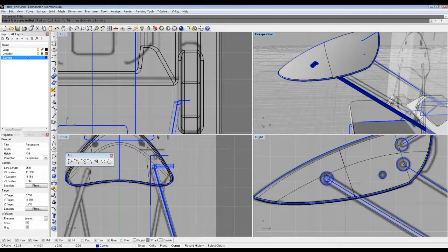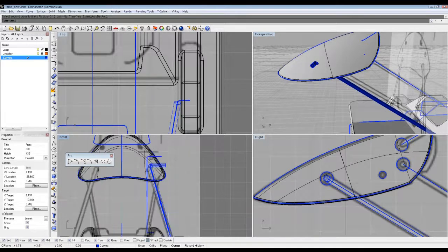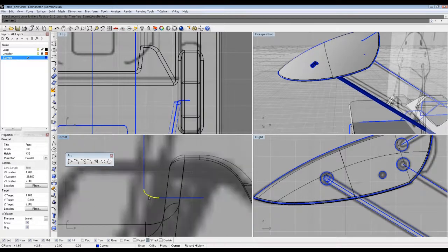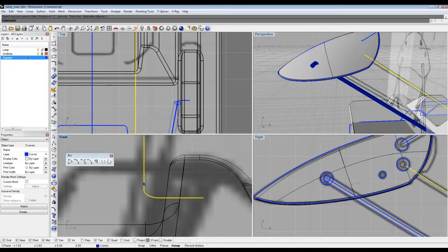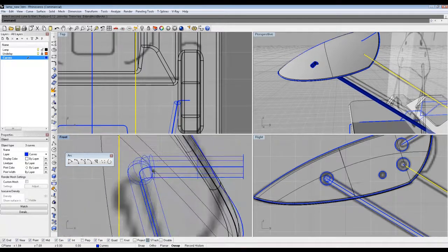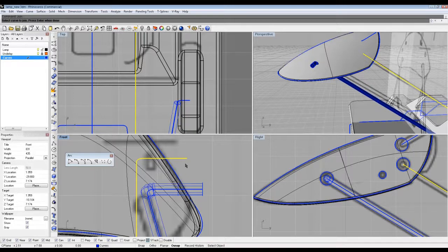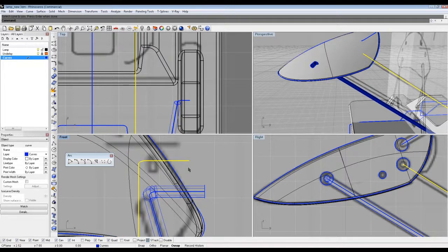And it's the other cool thing about when you're working in Rhino is that it remembers your preferences. So these radiuses that I just made on this curve, they're going to match the one that I made before, because it was the last input into that command. And you can see here up at the top where it says radius 0.12. And that's really useful, because you're not having to constantly re-input new numbers. So I will pipe this, and again, same thing, it's going beyond the lamp.